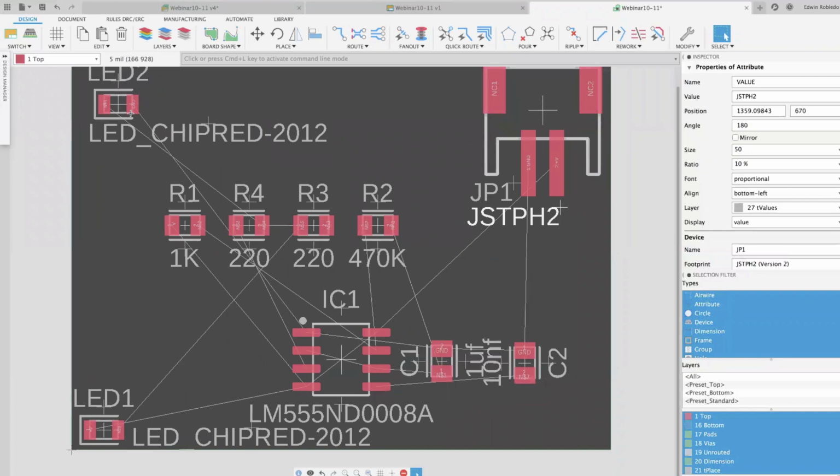Okay. Now, all these connections are referred to as signals. Just to let you know, when you transfer the schematic over to the board, they're referred to as signals. Now, this whole setup that you see here, all these connections, the term commonly used for all this is called rat's nest. So we're in rat's nest mode right now. All the connections don't have a trace.